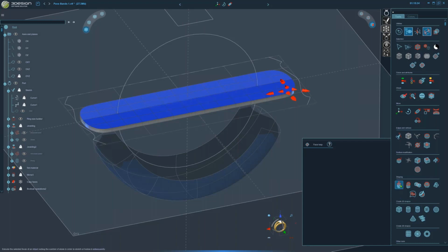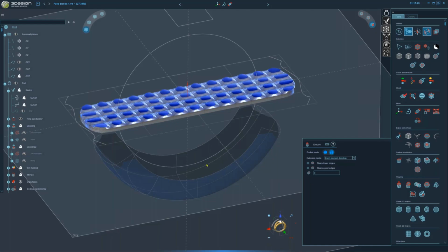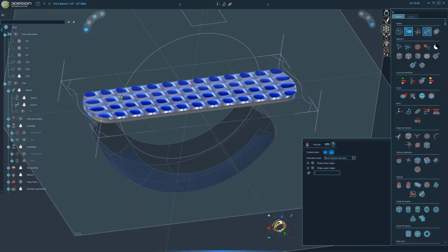So I click on my extrusion tool, and you can see here this pocket mode. You do all the faces at once, or you can split the faces. So if I click on that, pull up on here, you can see this cool little pattern comes up. Each face gets extruded. Okay, so that's going to be my texture. I'm keeping it very simple here, but these nice little grids. We can always play around with how we design, especially with retopology, these shapes in here, and you can do other kinds of patterns and things.